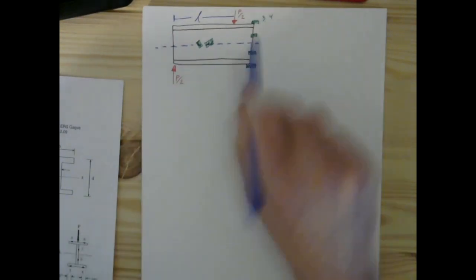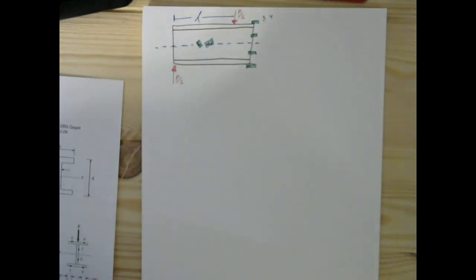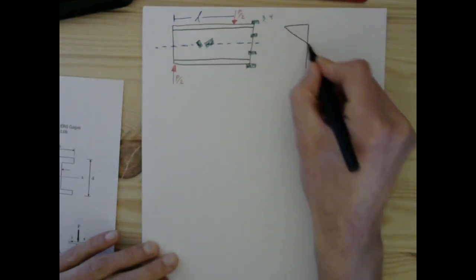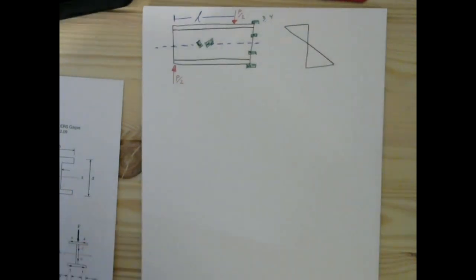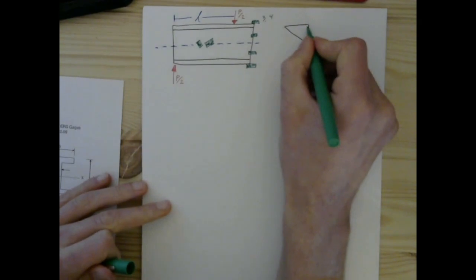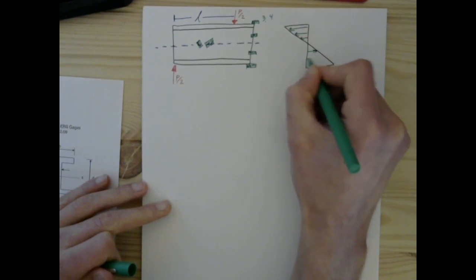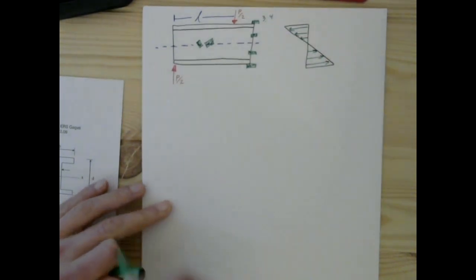Now, along this cut that we have made, we said that the moment was uniform and the shear was non-existent. So, our stress distribution will look like this. We're going to have compression on the top, and tension on the bottom. And it's going to be linearly distributed as long as we remain in the linear elastic region for the material, which we are absolutely going to do here.